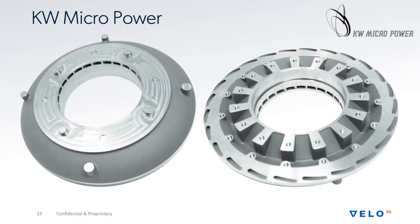But focusing mostly on the geometry, what you've got here, if you look on the left, is all these intake ports for some sort of impeller, that put a fluid in and turn it around in a sweeping pattern. And if you see this, call this upside down, more or less, you have the entrances in the middle, but the exits on the outside, and they sweep at very low angles, down to 10 degrees or even less in some cases. And so when you look at these really low angles, you can think about this kind of like a constrained plane.